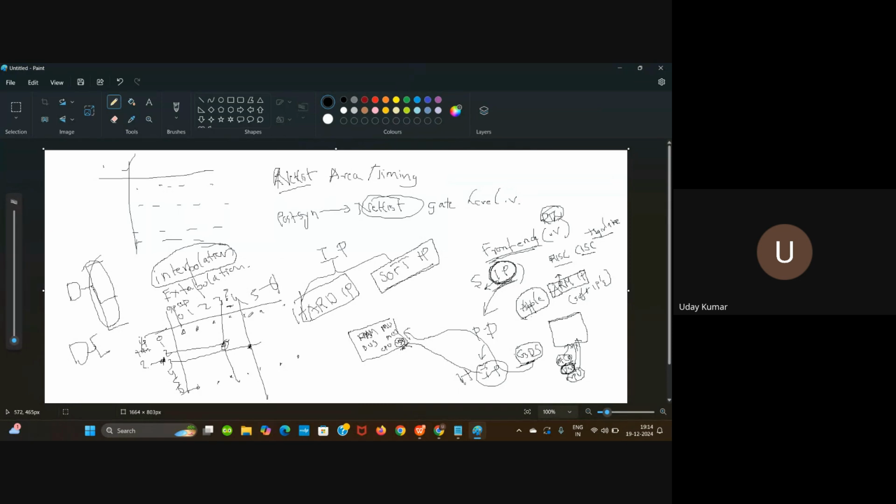If something exceeds 6, let us say, what will happen? Let us say we have lots of fan out, then this exceeds this 6, and the tool will try to extrapolate. When the tool is trying to extrapolate, it is very dangerous. It will impact your timing. It means the delay will be very big. So that's how the things work.